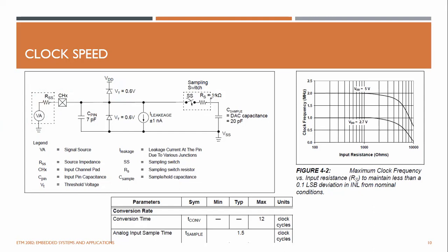And so ADC conversion sampling takes at least 1.5 clock periods. Like this is a complete clock, right? And this is another clock. Let's say this is clock number 1. This period is clock number 1, and this period is clock number 2. And in order to make sampling and holding, it takes 1.5 clock cycles, which means from this point to this point, so it takes time from here to here.